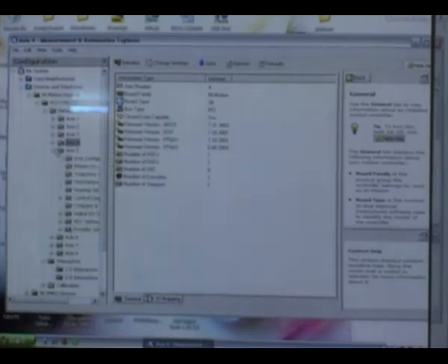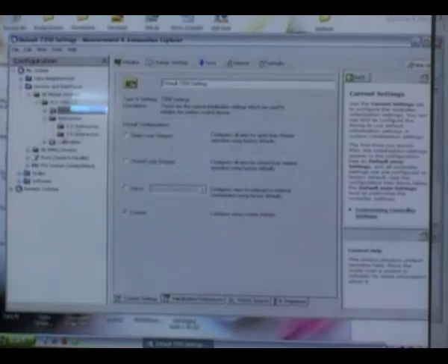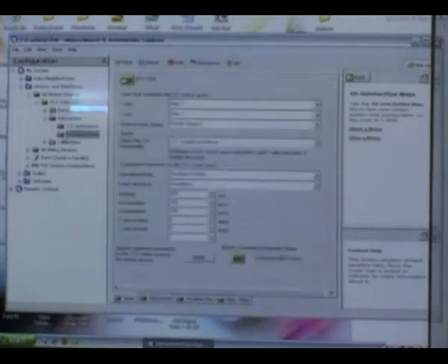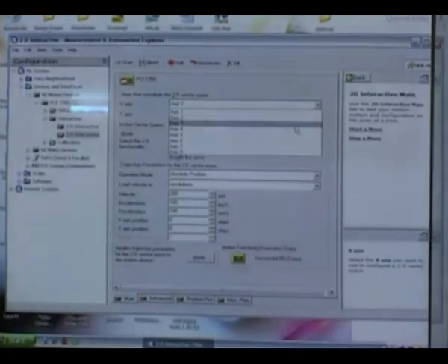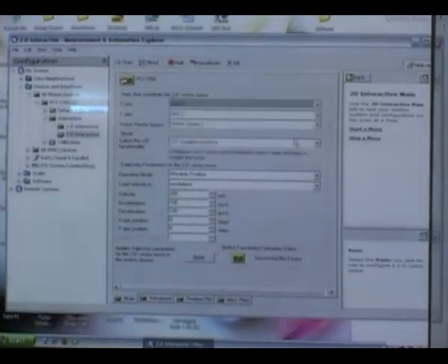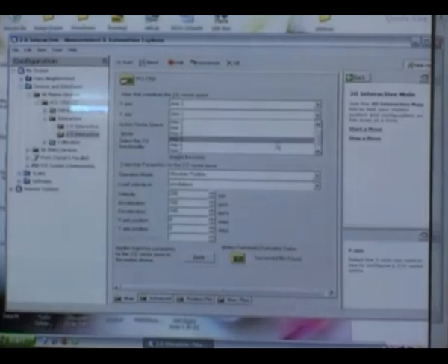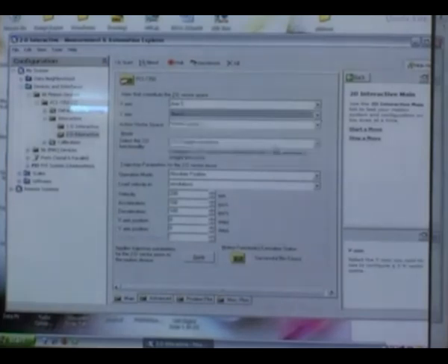We can move axis 4 in the interactive mode. So I will now go to the interactive 1D, or I can go to the 2D interface mode. Here I will change the definition, as axis 5 is configured to the X axis and axis 6 is configured to the Y axis.